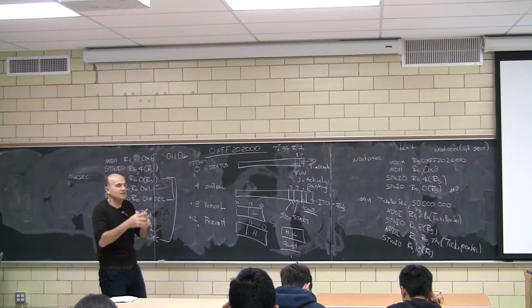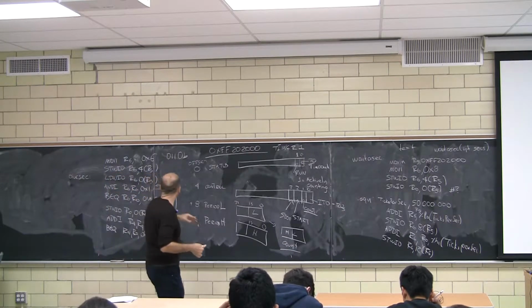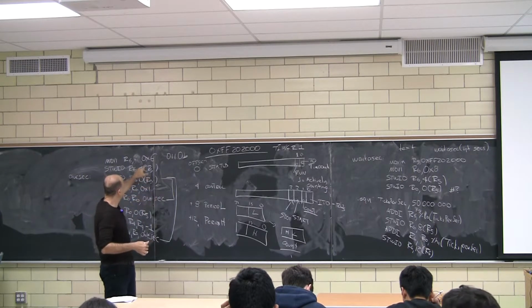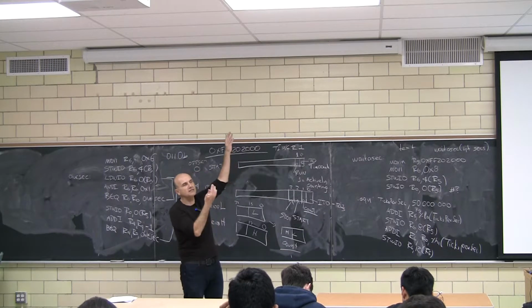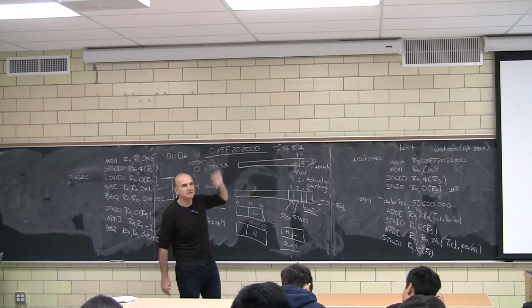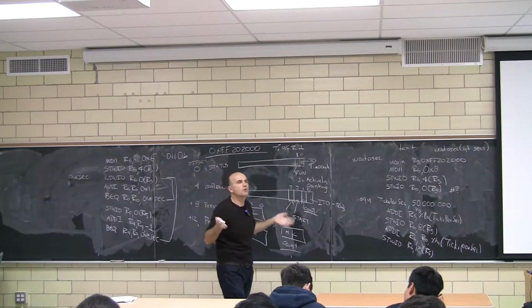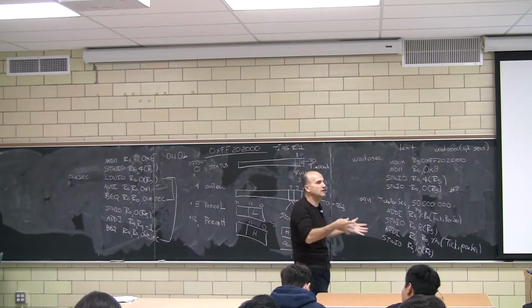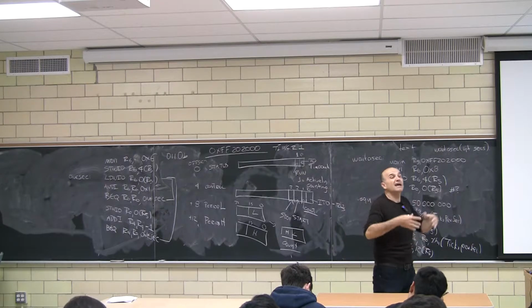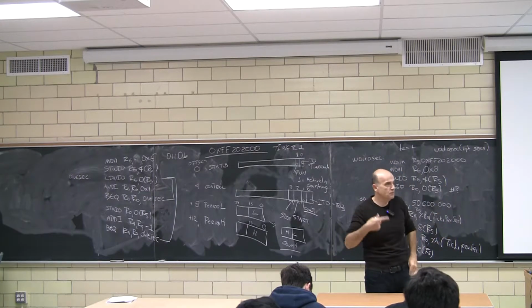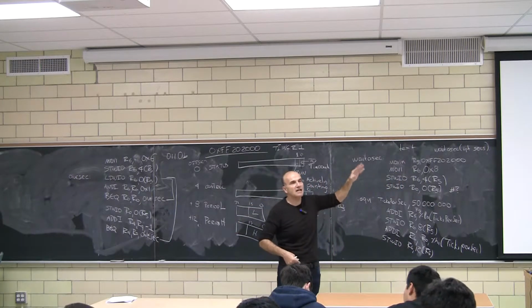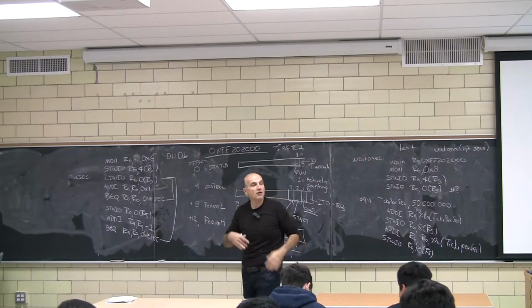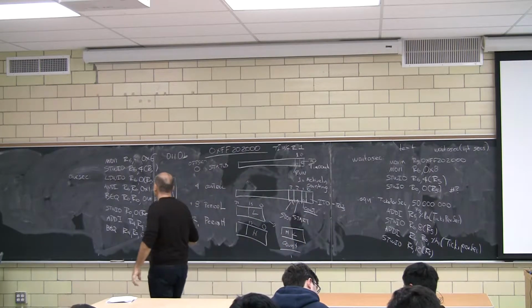Okay. The counter is counting on its own without worrying whether we are looking at it or not. The moment we fired off this 6, we said, keep counting 1 second. Anytime there is a second, raise your hand. If your hand is already raised, don't bother. Keep it there. That's it. Okay. And then we go and we look at it at some point. All we know is that since the last time we looked at the hand that was up, at least 1 second has passed. That's what we know from the CPU perspective. However, the timer will religiously raise its hand every second without any worries about how the CPU reacts to it or not. So far, so good?